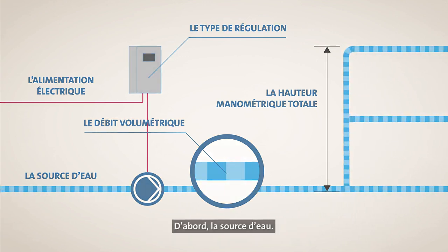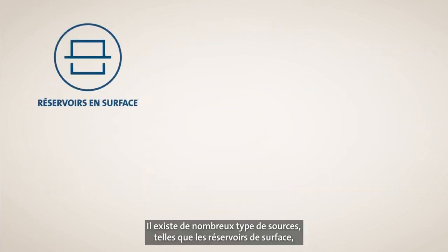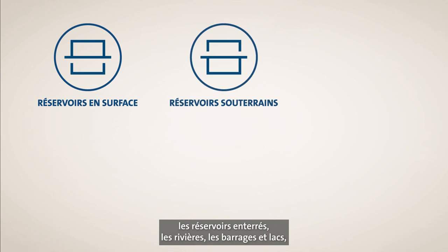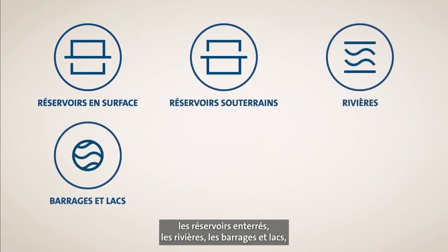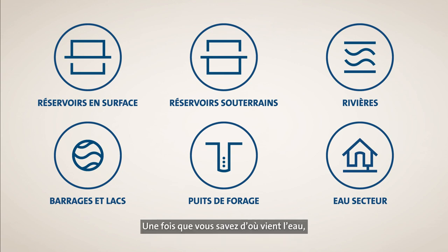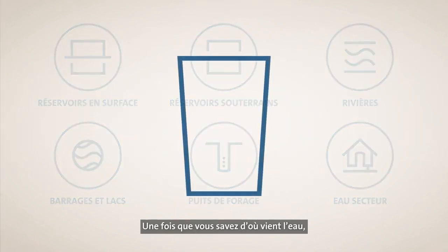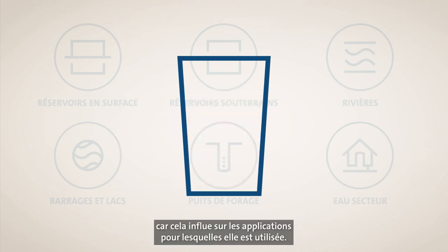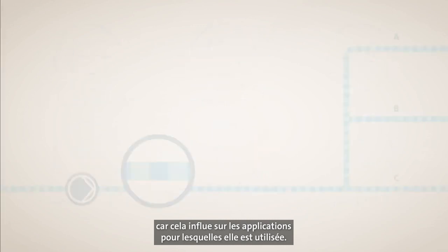First up, the water source. There are a number of water sources including above-ground tanks, underground tanks, rivers, dams, lakes, boreholes, or mains water boosting. Once you've established where your water comes from, you need to consider whether the water is potable or non-potable, as that has a bearing on the application in which it can be used.